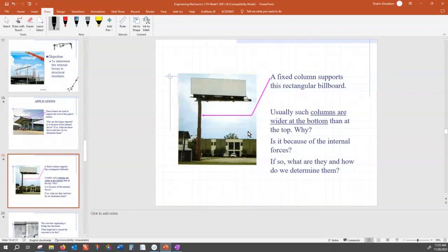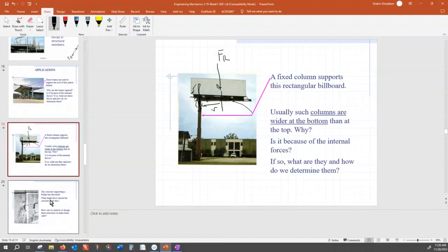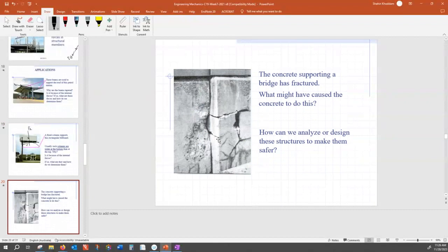And what type of load is that? It's a distributed load. So to find the reaction here, you have to substitute that distributed load with one single load and the line of action. And then you can find out this is like a cantilever. This is a cantilever fixed to here. And then that will change the radius of curvature like that. Okay? So that step only requires visualization. All right, so here we have an important observation.